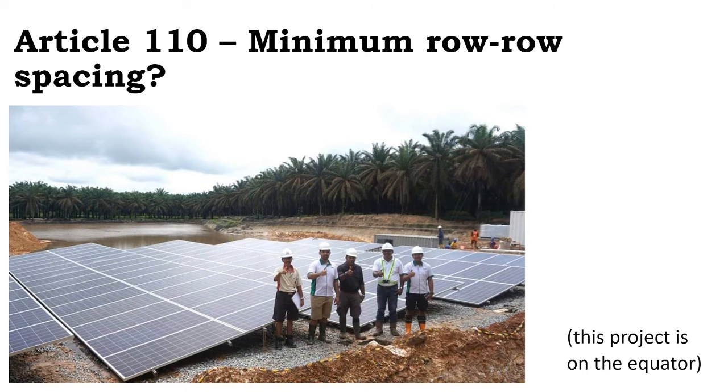So thinking about things like dedicated equipment servicing space, should there be 3 feet between rows of panels so that you can walk up and down and service this equipment? I guess you might argue that the equipment doesn't have any serviceable parts during normal operation. There's no breakers, there's no boxes, but I don't know. There are connectors. I haven't seen anyone enforce a 3-foot requirement on row spacing,